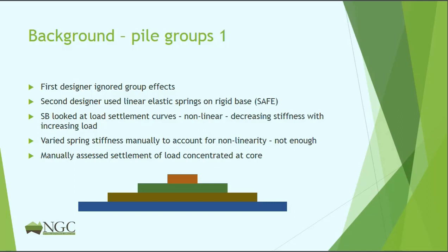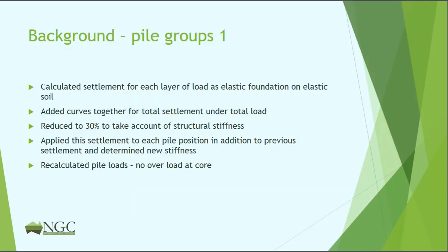and I did some hand calculations and calculated the settlement of an elastic foundation on an elastic soil for each of those 4 increments of load. And then I added the settlement curves together to give me a guesstimate of the total settlement of an elastic foundation under that load. And then I said, well, it's not an elastic foundation.